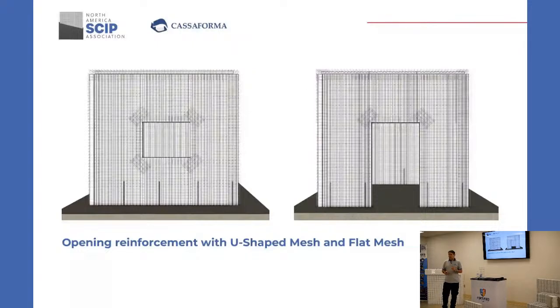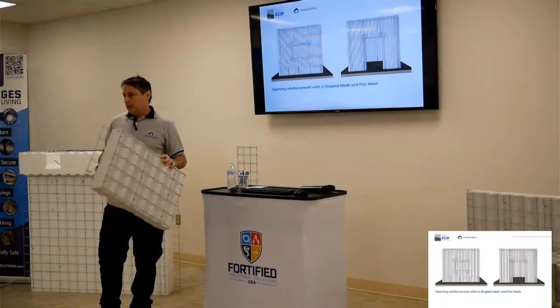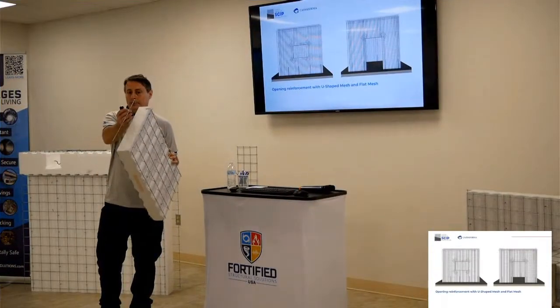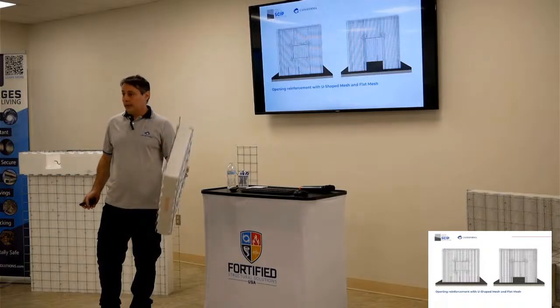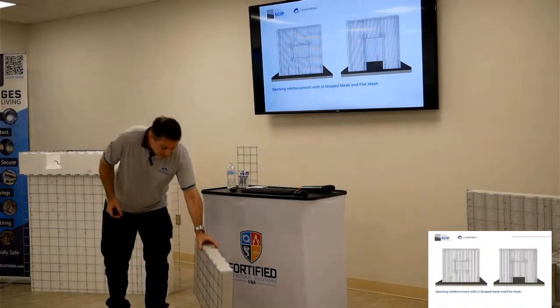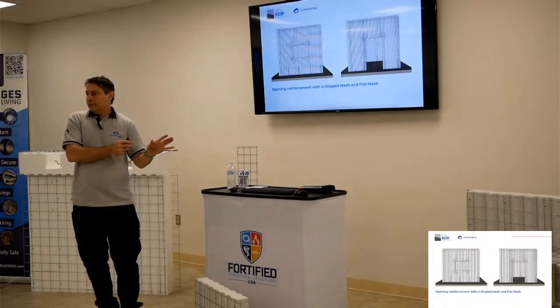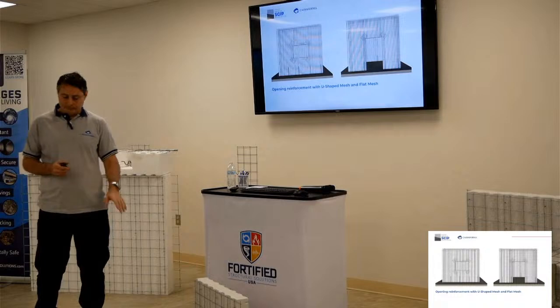And one important thing that people may sometimes ask is how I connect panel to panel. Well, they have their overlapping, one side to the other. I don't have it here because this is a cut. But if it were an entire panel, you would have the overlapping here, and here we have it the other way. So usually speaking, you don't have to have any additional mesh to connect panel to panel. You're already covered on that.